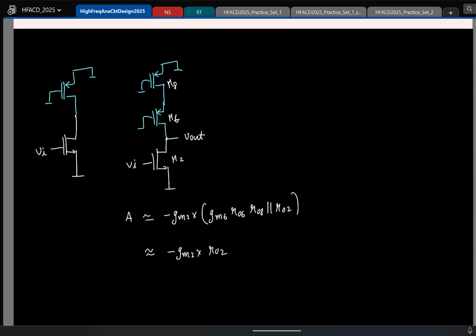Well, it looks like we did increase the output resistance here, but it seems like we are back to square one. And why is that so? Although we increased the output resistance, it seems like the final gain is only gm ro. So what is limiting the gain here? Looking up I increased the output resistance, but looking down it is still the same old ro. So what do you suggest we can do to increase the resistance looking down?